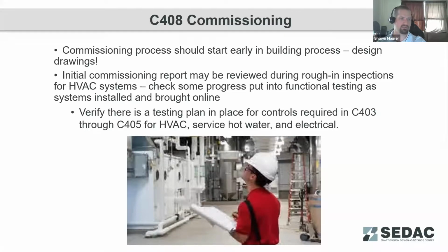There is a lot of automation, again, as noted, more and more relying on automation to achieve higher efficiency in our buildings. So we've got thermostat settings, unoccupied setbacks, demand control ventilation, economizers, freeze protection systems, all need to be checked and documented. So having an effective plan in place early is very important.